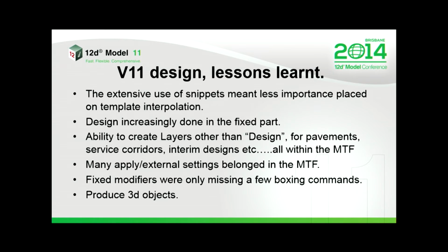And yeah, lessons learnt when we approached V11. Snippets meant that the old templates were becoming less important. The one reason you still needed templates in V10 was, say, transition between two curb and gutter shapes. You still couldn't do that. It was becoming increasingly clear that we wanted to do all the design in the fixed part of the template. Remember the order of execution: once we went to the decisionals, we couldn't come back in the fix.